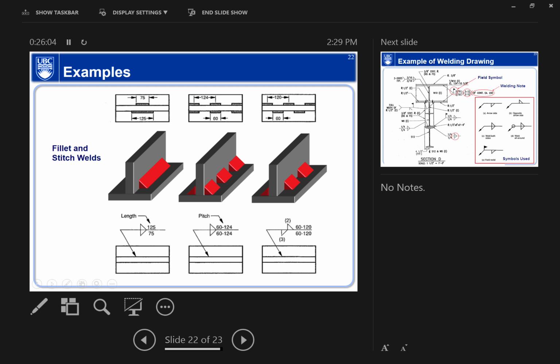If you have a really long joint, and your analysis shows you don't really need to weld all the way from this end to the other end, then you don't need to. So that's part of the analysis: how long the weld should be. Another analysis is how high the leg edge should be.